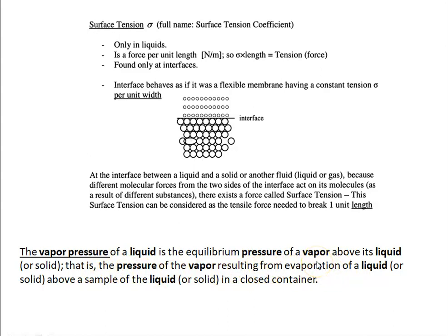So last time I explained, you have a water pot, and it is half filled with water. If you put some heat on the bottom, then it will start evaporating at 100 degrees centigrade. That vapor will try to escape, so it will come up and try to escape. But when the water pot is completely sealed, it can't go up. It can't escape. So what will happen eventually is it will go down, and it will create some sort of pressure on the water surface. So that was the vapor pressure.